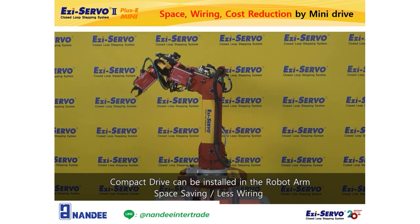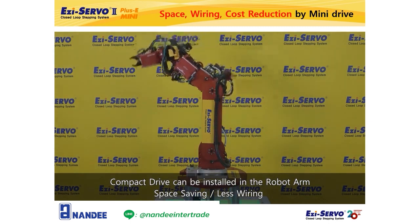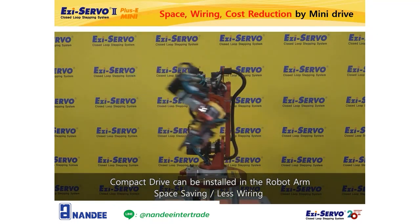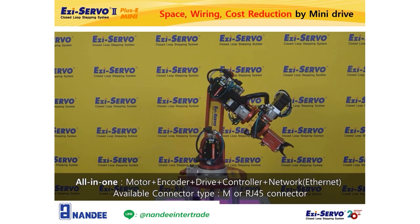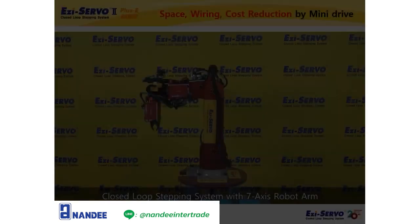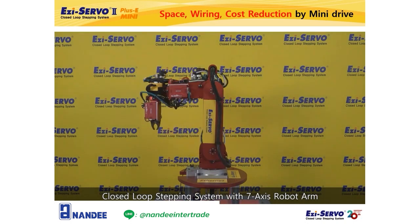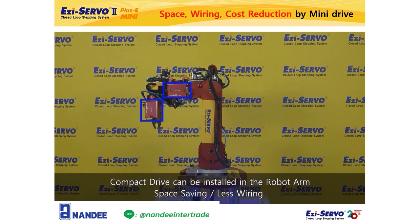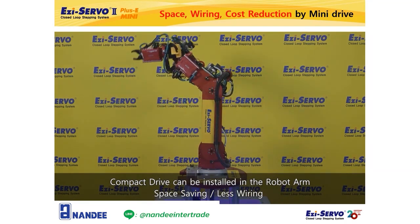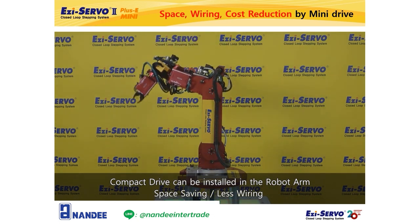In addition, there is no need to wire a motor and encoder because an Easy Servo 2 Plus E-All, an all-in-one product that combines a motor, high-resolution encoder, drive, motion controller and Ethernet network, is applied to 5 out of 7 axes. Therefore, when using the mini drive Easy Servo 2 Plus E-Mini and the all-in-one drive motor, there is no need for a separate control box.